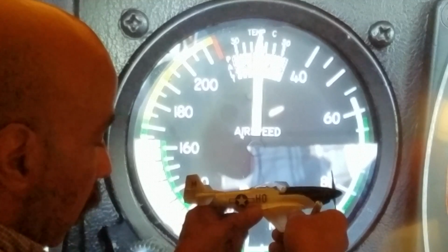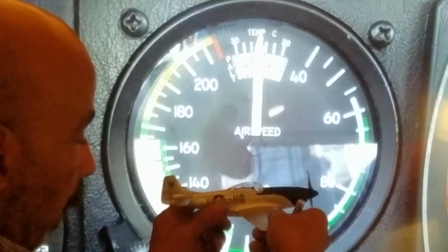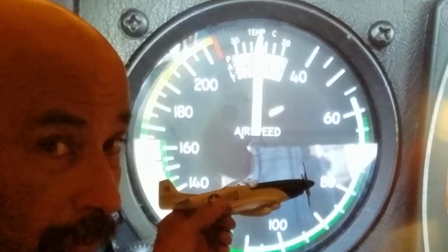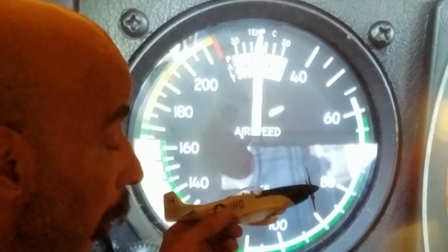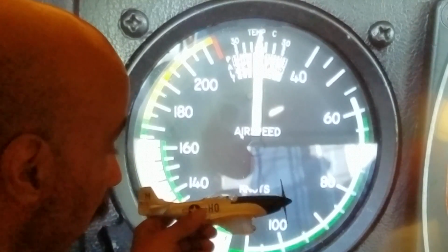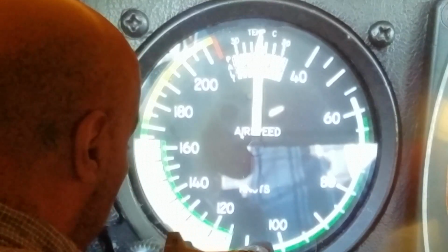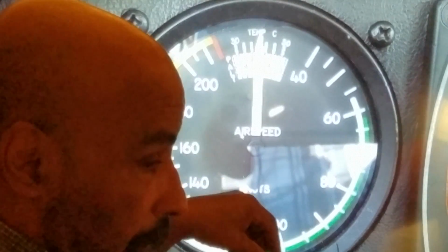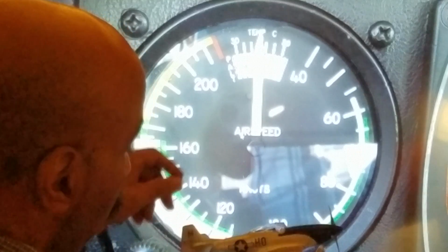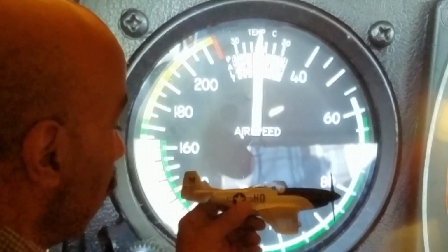Beyond that takeoff position, if the flaps were fully extended, they become speed brakes and you might never get off the ground. Or if you did, you'd only stay in ground effect and not be able to climb out of the airport area. You might run into a building or something if you try taking off with more than takeoff flaps.